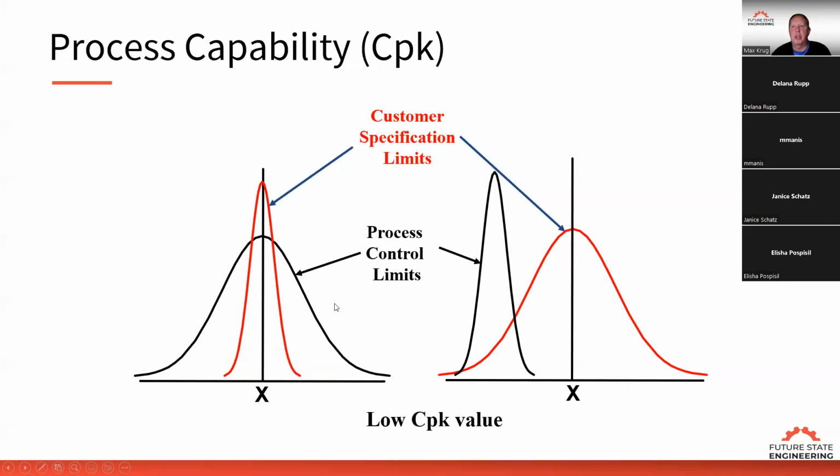Okay, so when we're looking at process capability, you have to use the two in combination. I might have a customer call me up and say, we've got a problem with a lot of scrap on this process. And I say, okay, did you measure the process capability? They say, yep. So I say, okay, my first question is always, what's the CPK? And they say, the CPK is 0.8. Okay. So my second question always is, what's the CP? They say, the CP is 1.5.